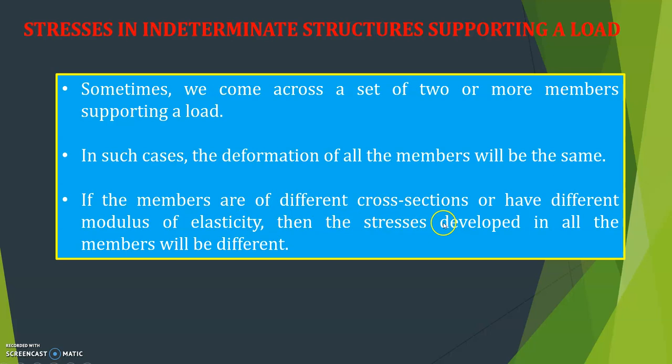If the members are of different cross sections or have different modulus of elasticity, then the stresses developed in all the members will be different. So this point you have to remember. Then you have to find what are the stresses developed in each bar.